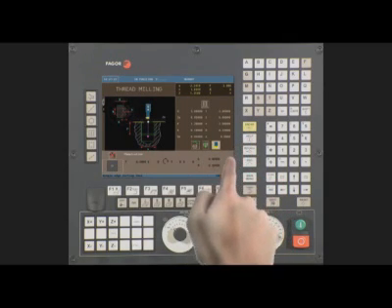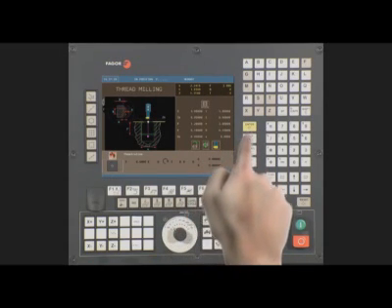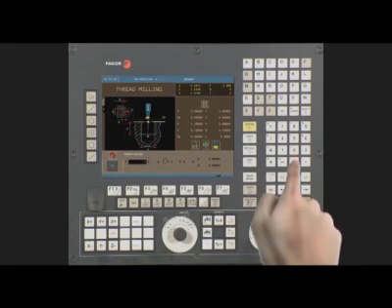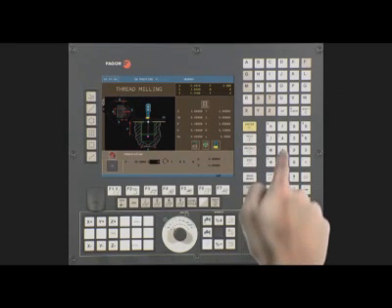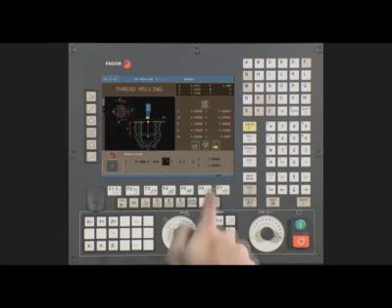Use the half key to select a single edge cutting tool for our operation. Use the half key to select coolant off. F. This is the feed rate. In this case, it is 20 inches per minute. S is the spindle RPM. We'll be running at 1000 RPMs. Using the half key, select clockwise spindle rotation.